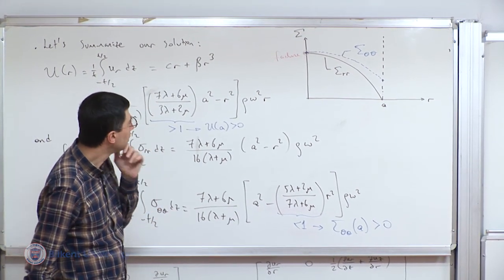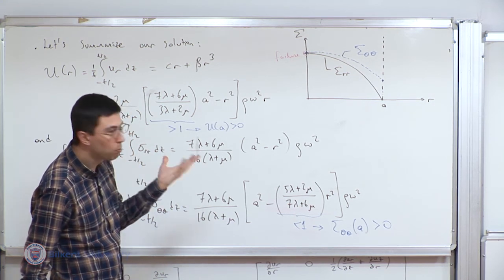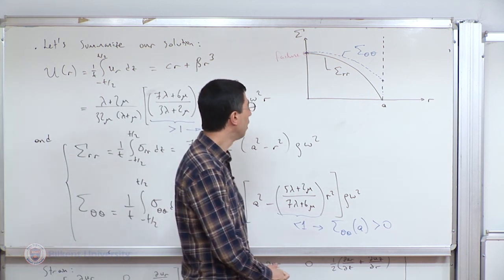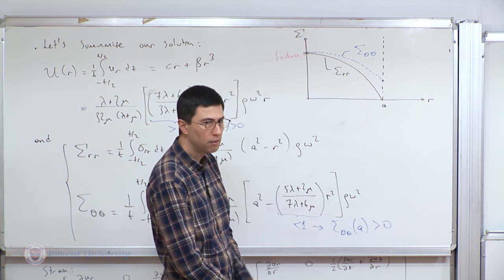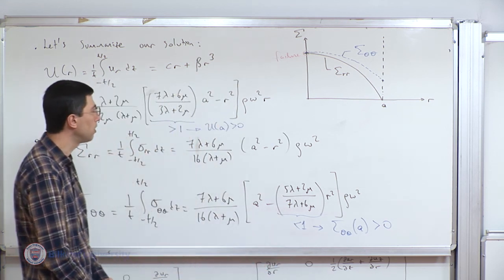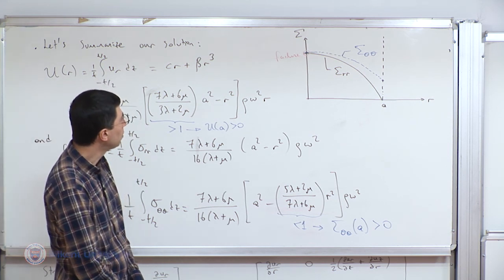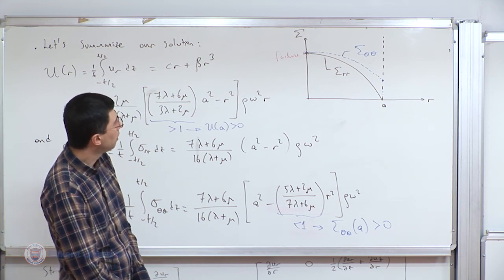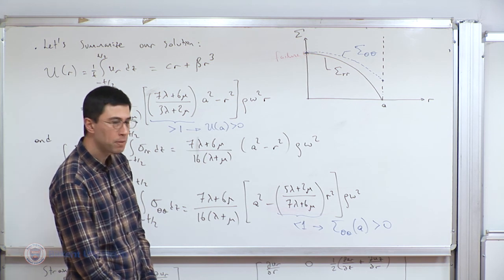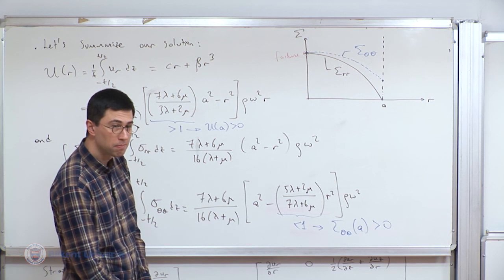And if it's brittle, then the normal stresses matter, and these are the normal stresses, so the maximum normal stress would determine failure. If it's ductile, you would have to look at the von Mises criterion or some shear stresses in that case. Perhaps that's not the maximum point, the most critical point, but that is at least one critical point to worry about depending on your material. Okay? Questions?